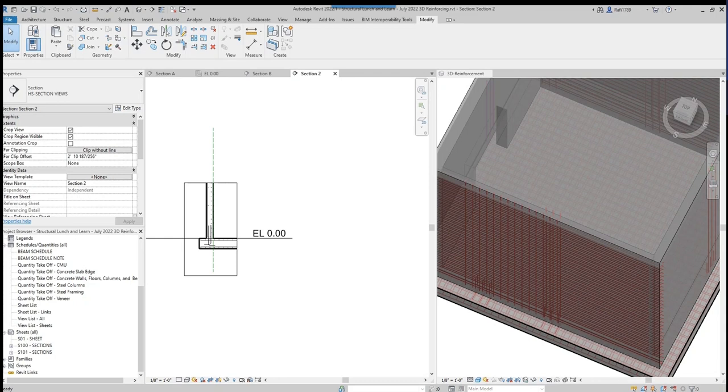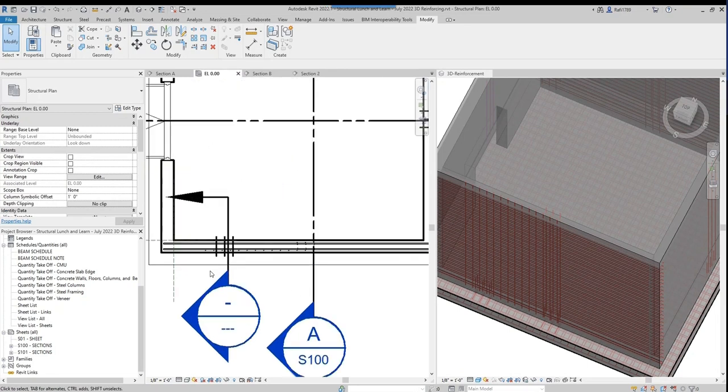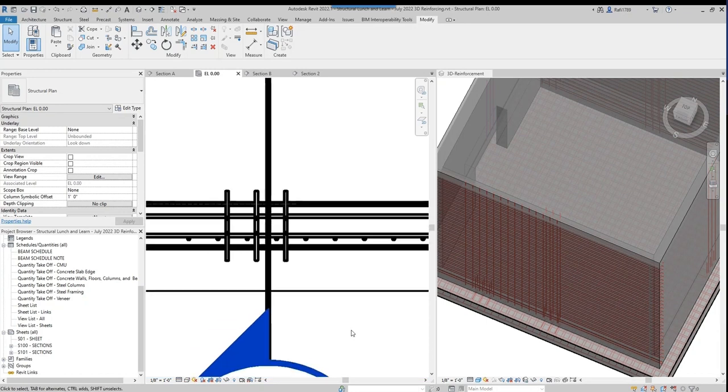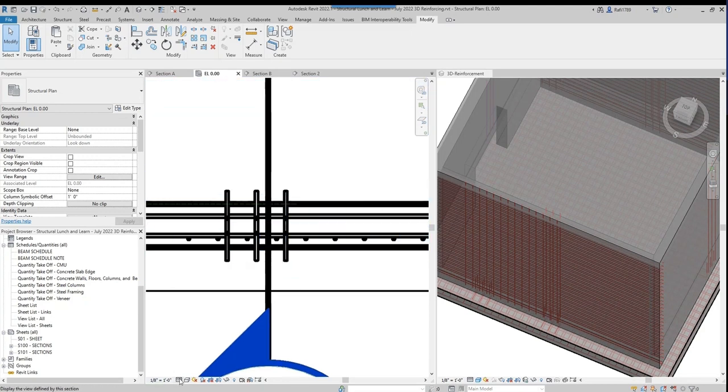Any questions so far with that? I do have a question about, when you're on the plan view for that small building, it's not entirely related to rebar. The way it's graphically showing up, if you zoom in, the bars look kind of different in how they're drawn out. Like it shows the whole bar instead of just the line. Yeah, that's representing your detail level. So if I change this to coarse, it's going to be single lines.